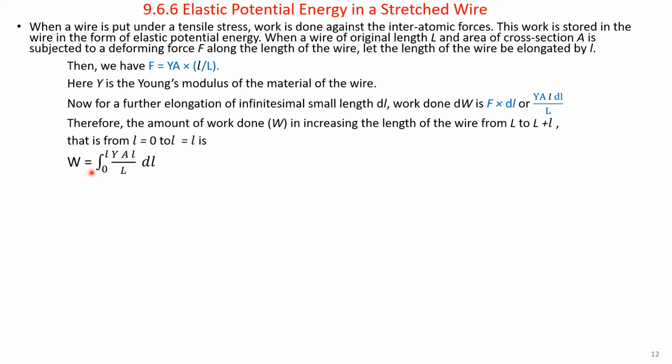W is equal to the integral from 0 to l of YAl divided by capital L into dl. Here Y is the Young's modulus, A is the area, small l is the change in length or elongation, capital L is the original length, and dl is the differential.